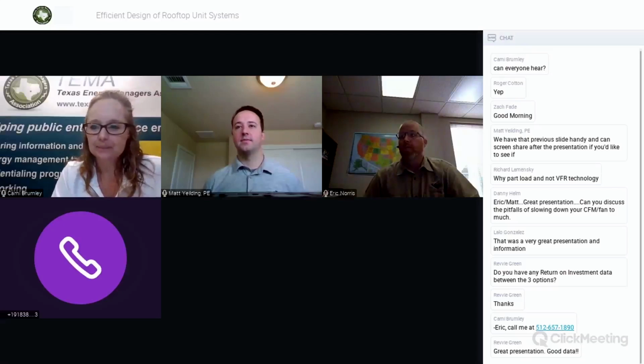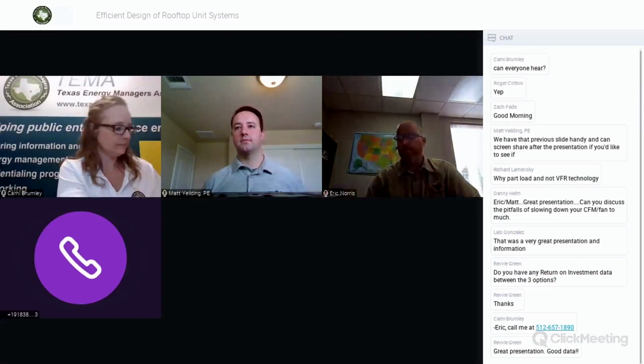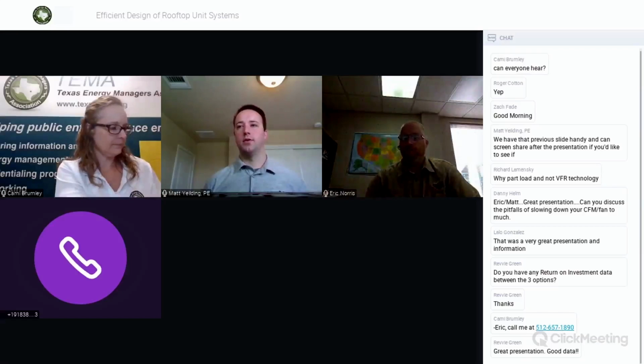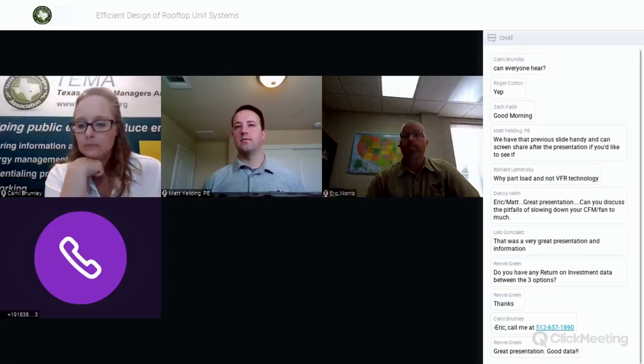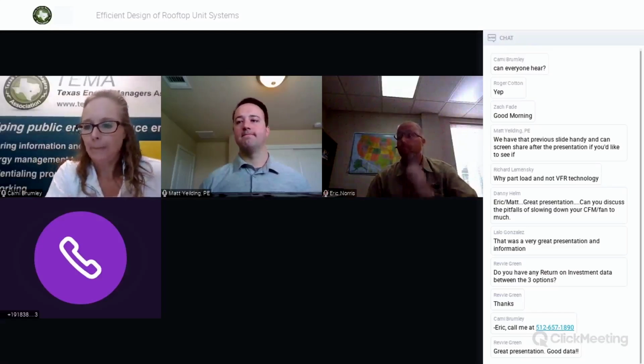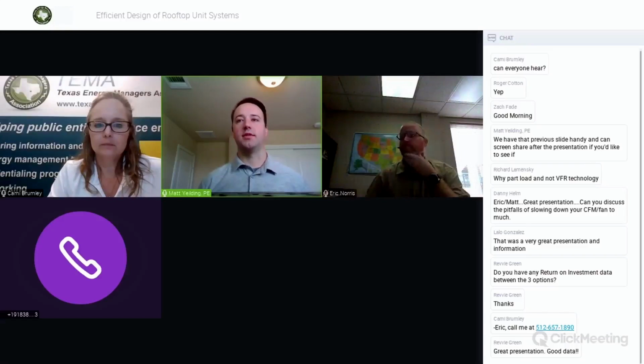One other thing that really needs to be looked at as you go into any VAV system is your diffuser selection. You need to make sure you've got adequate throw on your diffusers to get good mixing in the space, where you're not just dumping that cold air out of the diffuser onto whoever happens to be below it. So it's got to be reviewed during design. As long as it's designed appropriately, it shouldn't be a problem, as with any other VAV system. This is not a wildly out there type system, where the majority of good MEP engineers aren't going to understand those concepts.